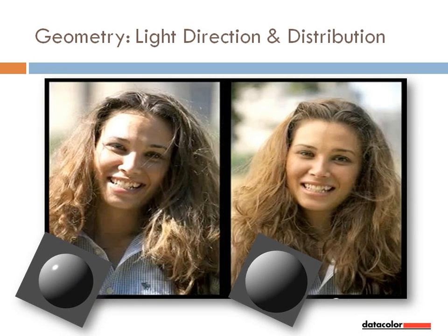Lighting geometry is important in measurement for the same reasons it's important in visual evaluations. Diffuse light minimizes effects of texture and gloss. Direct lighting shows them off. It emphasizes the differences in shape and texture. And those differences will show up in your color numbers.